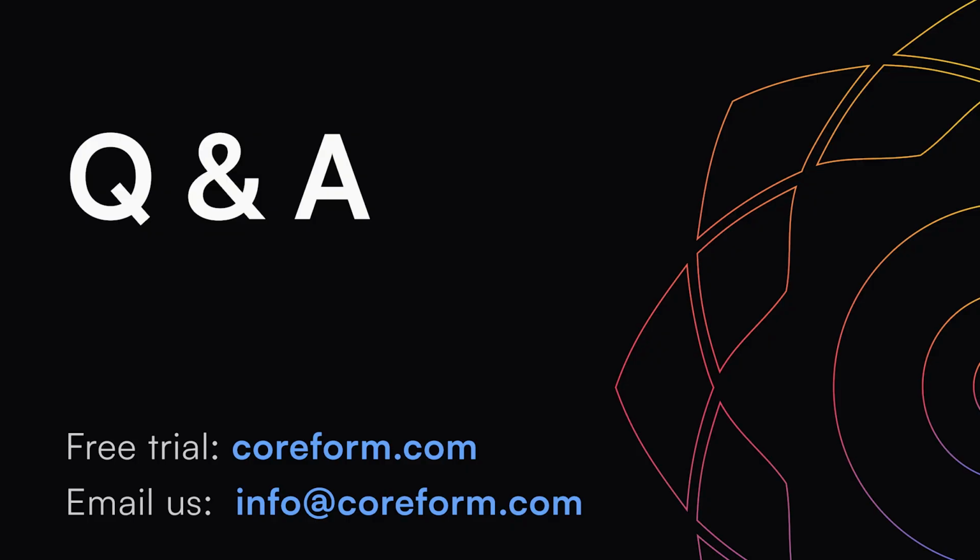Okay. If I have a multi-part assembly, do I have to use the same global mesh and mesh size for the entire assembly? No, each instance can have its own mesh. So if you use instance-based modeling, you could provide a different mesh per instance. Here I did a single part, multiple cell approach as a way to have an efficient modeling of the interfaces between the pin, seal, and headers.